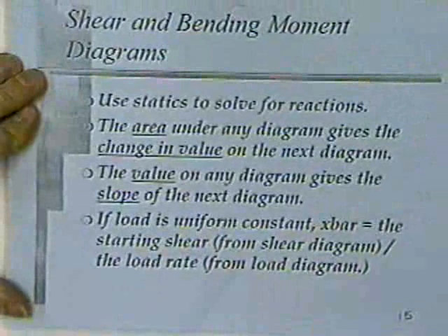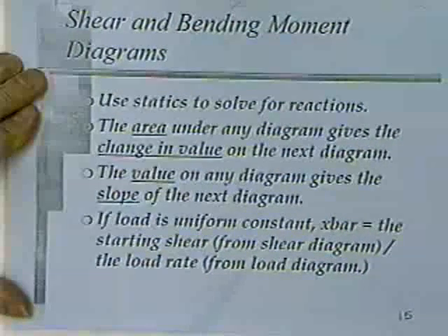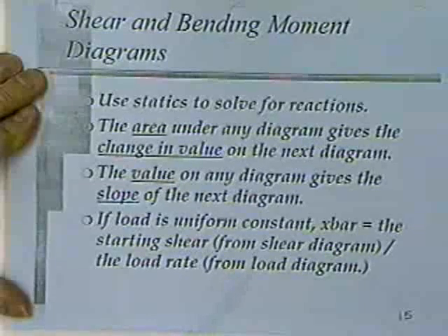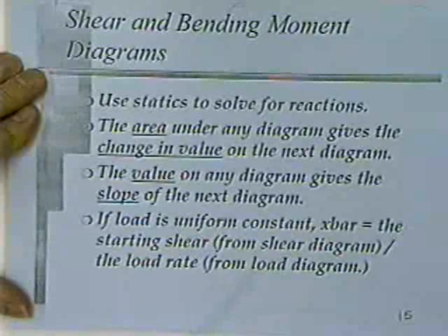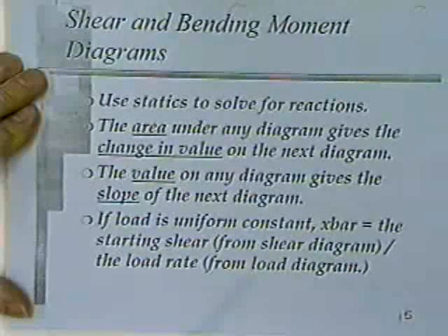Beams, on the other hand, usually have a continual change in the magnitude of how badly they're bent and how badly they are sheared. And in those cases, rather than being discrete changes in the magnitudes, there are continuous changes in the magnitude, and you need to be able to draw shear and bending moment diagrams in order to solve for the worst case.